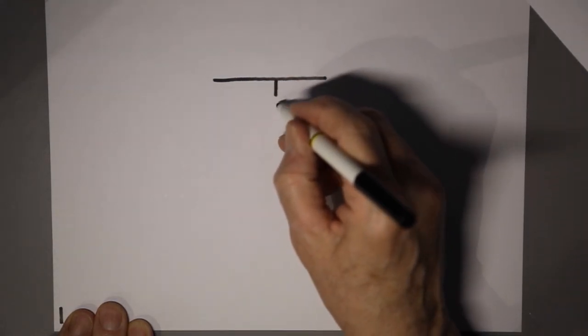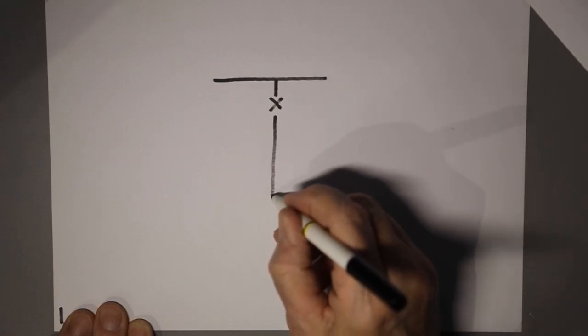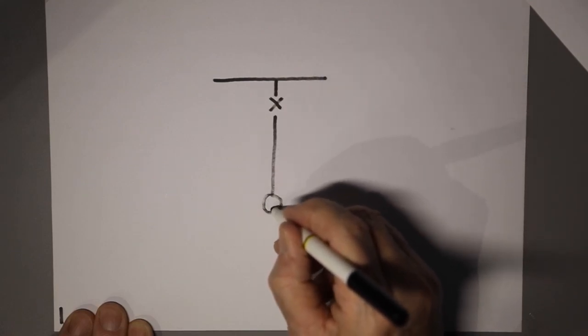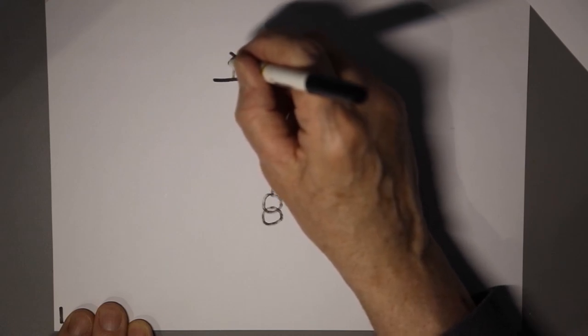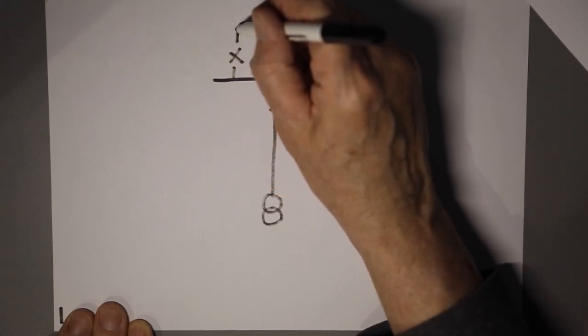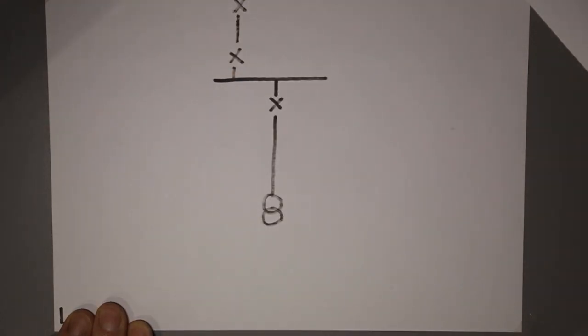There's the, let's say, 11 kV busbar with a circuit breaker that then feeds down a cable to a transformer. We'll also do an incoming circuit breaker, and then right at the top of the picture there is a DNO circuit breaker operated and controlled by the DNO.